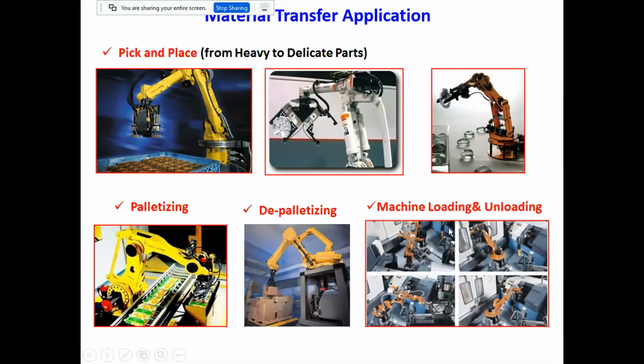Machine loading and unloading technology. Robots, you will see the one robot. This is called a robotic work cell, friends. Here, what it includes: basically the robotic work cell consists of a single robot, so many production machines, and some form of delivery systems. Then the same robot is serving 2-3 machines at a time, meaning such robots require a higher level of degrees of freedom and a higher level of intelligence as compared to pick and place robots.